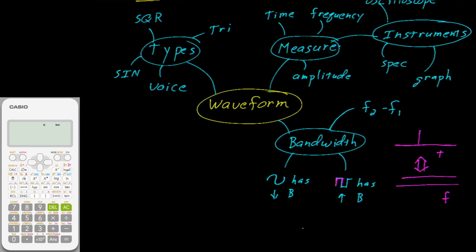We see these discontinuities in other places. For example, in power electronics, there is a device called a silicon-controlled rectifier, or a triac. And it might give you a waveform that looks like this. It basically takes a sinusoid and cuts it off. Anyway, you get this transition here, this rising edge. And you can see that that has a very large bandwidth.